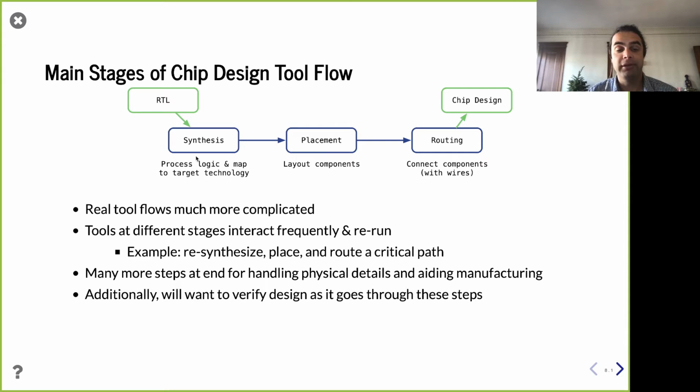Now I've chosen the resources I want. I need to figure out how to put them down in 2D. And as we'll see very soon, hopefully, perhaps we'll be talking about how to place them in 3D. But for now, it's been 2D for decades, and maybe 2D for the remainder of the decade, but 3D is hopefully not too far off. So how can I go about placing these components in a way that makes sense, perhaps reduces the length of wires? Because the next step is actually running the wires.